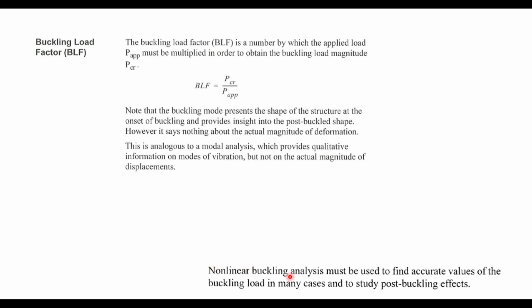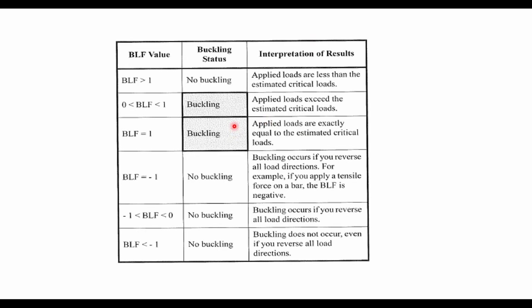Now as I said, nonlinear buckling analysis must be used in many cases to find accurate values of the buckling load and to capture post-buckling effects. Very important. In short, what are we going to get from this? Modal analysis provides quantitative information about the mode of vibration, but not the actual magnitude of the displacements. So you're going to get the mode shapes, that's all. It is not the magnitude of the displacement in linear buckling, it depends on whatever factor you consider here.